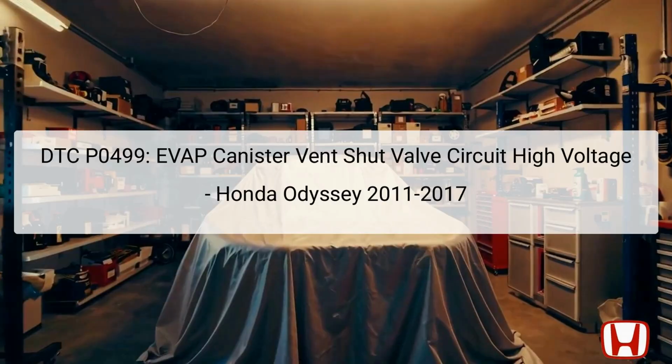The DTC P0499 indicates an issue with the EVAP canister vent shut valve circuit, specifically a high voltage condition. This valve is crucial for controlling the evaporation emission system by regulating the venting of fuel vapors from the EVAP canister to the engine during specific conditions. Typically located near the fuel tank, it can affect emissions performance if it malfunctions.